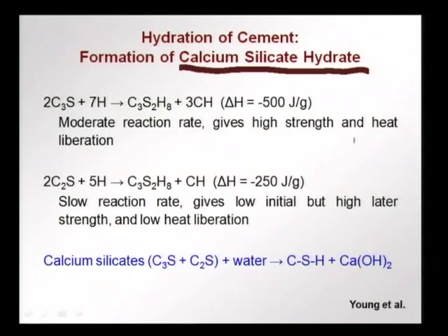We notice a couple of differences between these two reactions. First of all, when C3S reacts, there is more heat produced than when C2S reacts, and also we find that when C3S reacts with water, more calcium hydroxide is produced than when C2S reacts. So, these two differences have important consequences.